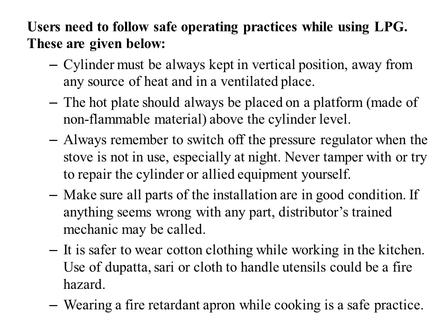We should make sure that all the parts of the installation are in good condition. Whatever relates to the wire or the piping that comes from the cylinder to the gas stove or any parts, it should be in good condition. And it's always safer to work in a kitchen while wearing cotton clothes, and using a dupatta, sari or cloth to handle utensils would be a fire hazard. There may be chances that it may catch fire. And the best practice is wearing a fire retardant or fire resistant apron while cooking, which is one of the safe practices.